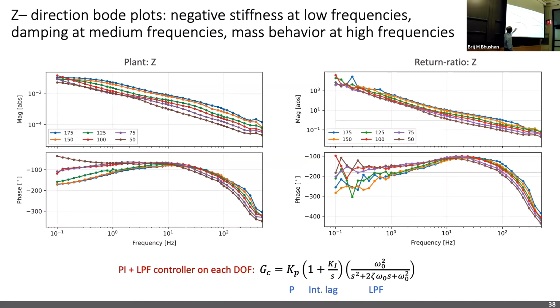A key thing to note is that all of these plots are going down, which shows the negative stiffness behavior, but at 50 microns, this begins to go up. And that is because we have actually made contact at some location. And now it's not negative stiffness anymore. There is actual stiffness due to contact. And that is to be expected because it is very hard to maintain something perfectly flat, and plus our floater is very flexible, and therefore it ends up making contact at small air gaps.